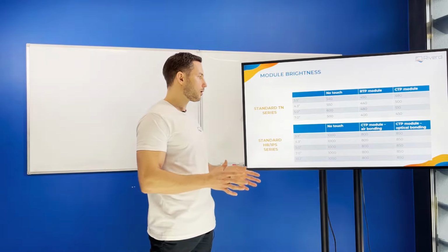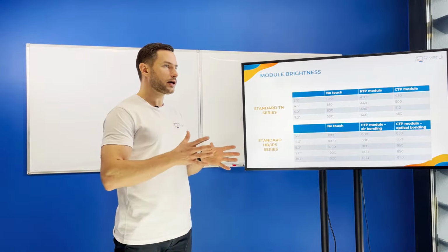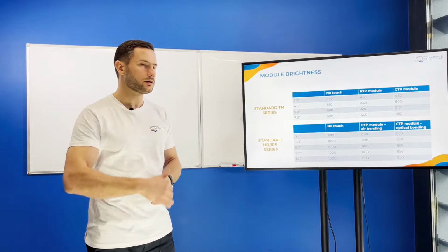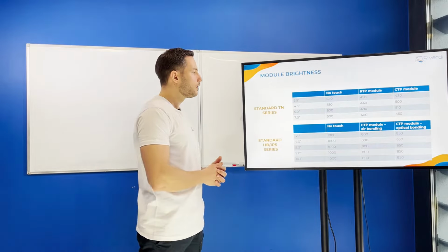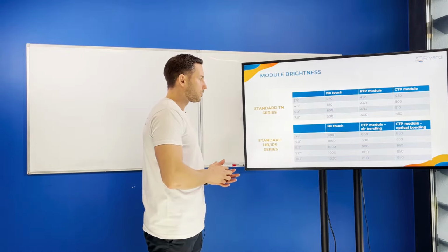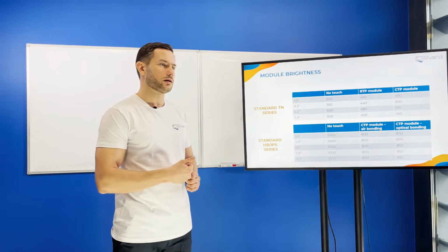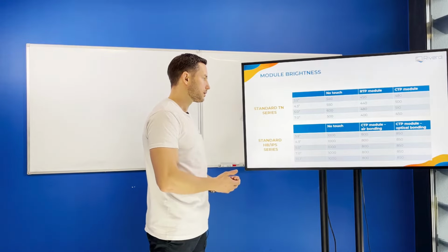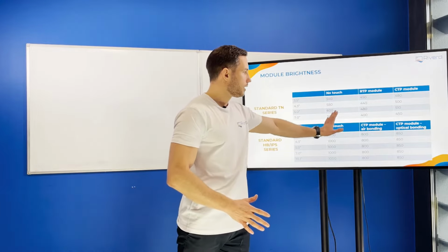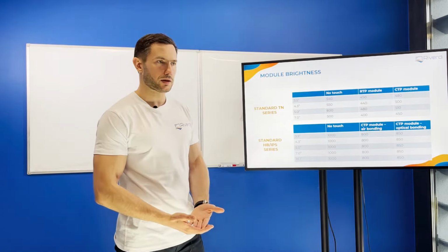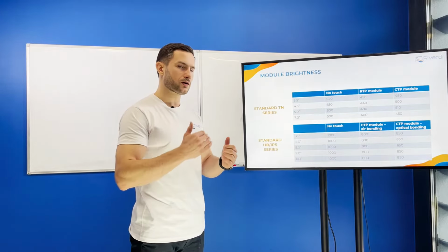And this 1000 candela also allows us to build outdoor devices, provided that we keep the reflections low, either by adding some shadow, so not having direct sunlight, or by adding some additional anti-reflective layer on the last surface. Yes, that will typically be glass. And as you can see in this table, if we add something on top of a display, like a typical touch screen, then the brightness goes lower because of these reflections.